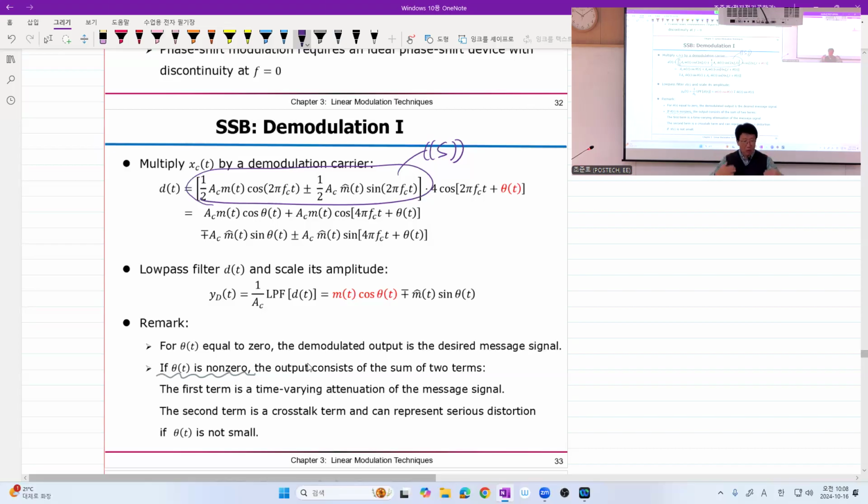Now, you let these two circuits go for 2 hours. What will happen? You use the oscilloscope again and see. Your phase difference of the two signals may be, again, very different. Got it? So just having two independent oscillators, even though they have no carrier frequency offset, there is no guarantee that you have no phase offset. It's almost impossible.